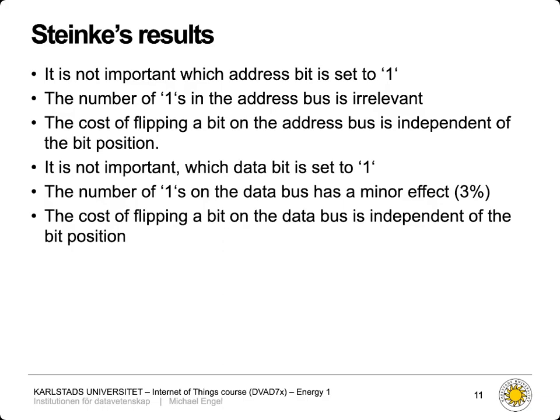And from this, you can build an energy model where you can input a piece of machine code, and then you can simulate that machine code, and you don't only get the functional result, for example, the number that was calculated, but in addition, you get information. When you have this model attached to a CPU simulator, then you get information like: this piece of code executed in that way consumes so and so many nanojoules of energy. And if you have this information, then you can use this to optimize energy, for example, in a compiler backend, as we'll see in the next lecture.